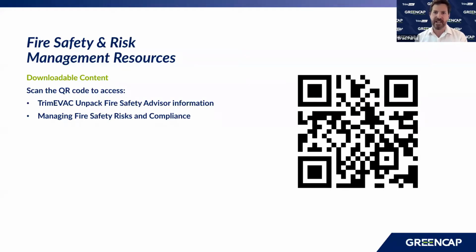So if it's an old building that hasn't been touched since 1st of July 1988, then that building won't need to produce an annual fire safety statement because it won't have a fire safety schedule. The concept of the fire safety schedule came about in 1988, and buildings developed or refurbed or constructed since then will have a fire safety schedule, and that was the trigger for annual statements.